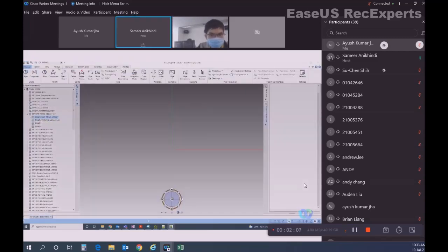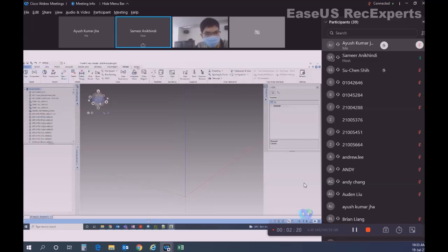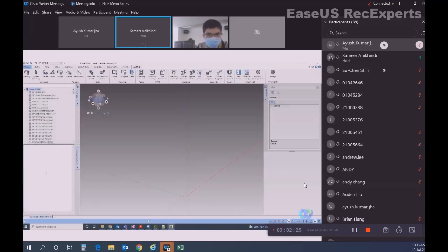Okay, so you can see this is my general user window. I'm in the piping application. You can see there's no admin tab over here, right? And this is my admin. I go to piping application. Here there is an additional admin tab. If you want to check which user you have logged in with, you can open tools, command window, and type Q USER. It will give you the current user. You can also check Q MDB. It will give you the current MDB, right?